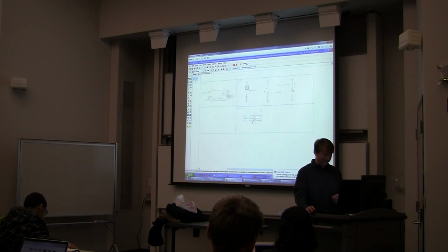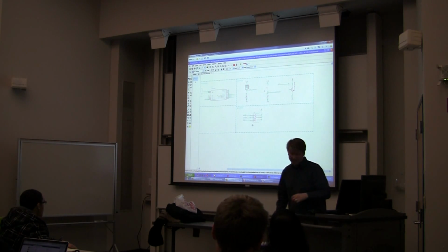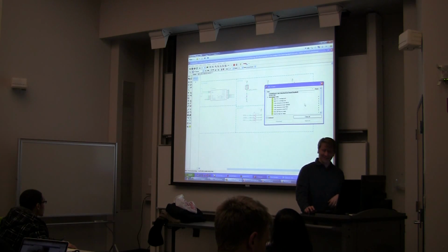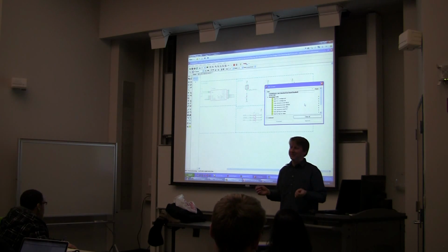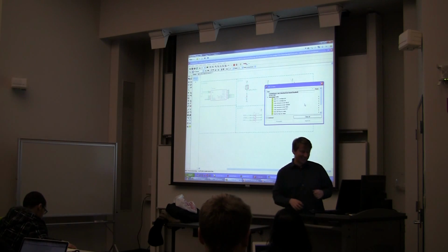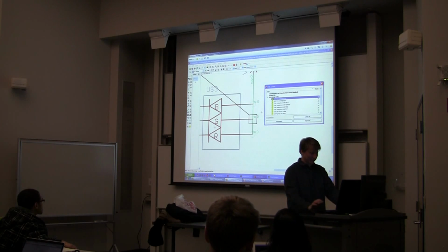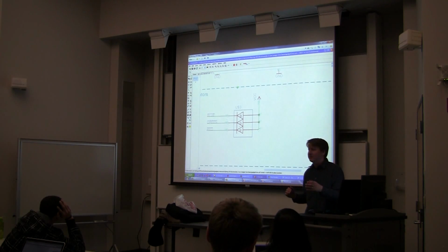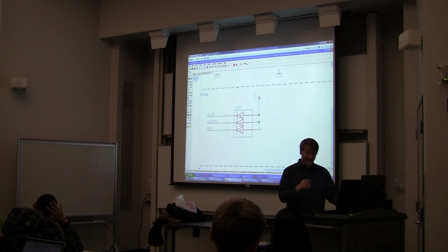Okay. So something that I have not been doing that you should be doing religiously is anytime you add a little bit of stuff, you want to be typing ERC. Because ERC will start to generate errors based on you doing the wrong thing. And it's really disheartening to do your whole thing and then find you've been doing something wrong every single time. So that's bad. And a lot of these can be real errors. So here, net VCC overlaps pin. It's like, oh, I know what I forgot to do. I forgot the junctions. And those are very good errors because there are other errors that give the same warning but have a very different problem. So you want to make sure you just get rid of all of those.